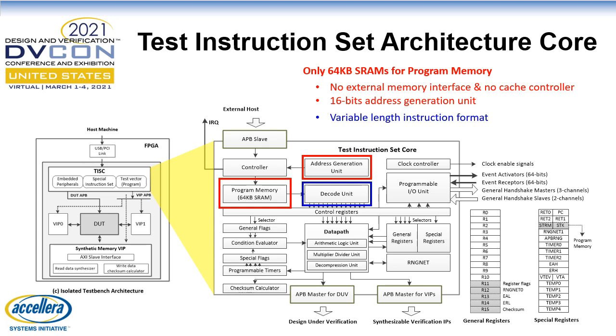A configuration register access could be encoded into various instruction formats of different byte lengths, considering their addresses, write data, and relationship with the previous instructions. Special instructions, such as repeated APB accesses with automatically increasing addresses, are very effective for reducing test program size.